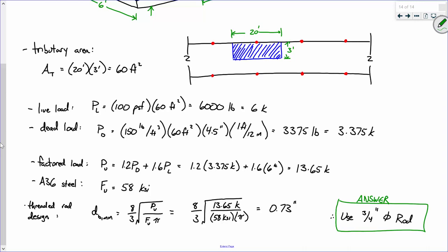Well, that's what this is. If you want, you can take a 3/4 inch diameter rod and calculate FRN. What you'll find is it's going to be a little bit larger than this. You really don't have to go through and do that, though, because unlike the tension member, there weren't really any assumptions made. With the tension member, we were having to assume a thickness, like we just said, let's take the effective net area and make it about 75% of the gross area.